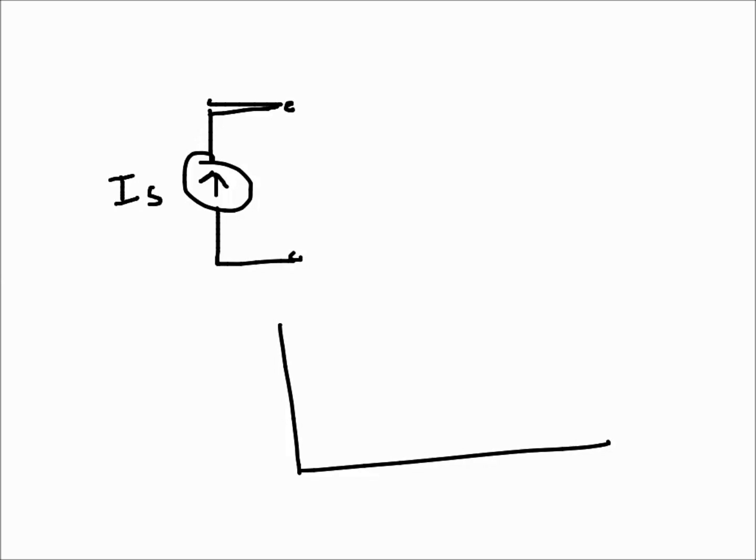Now, a current source is something that maintains a constant current through its terminals, irrespective of what is connected to it. For a current source it becomes something like this. If this is I, and V here, the axes have changed. If you have noticed, I is constant here, it doesn't change. Whatever the voltage is, the voltage depends on whatever is connected across it.